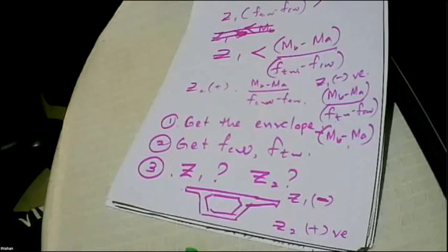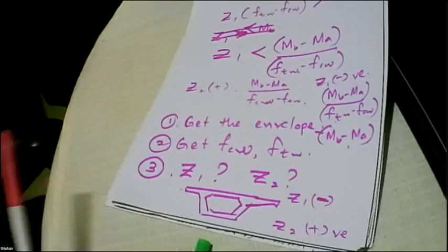So basically we don't need a chart like that, because nobody can draw charts for box girders, because everything is variable. That will all depend on practical considerations, because we are not talking about very small members. We are talking about massive members over large spans. So the design engineer might do so many things to optimize it. Even this angle for the chamfer is not known. That will all be decided by the design engineer. So basically nobody can develop any charts for box girders. But we don't need it.